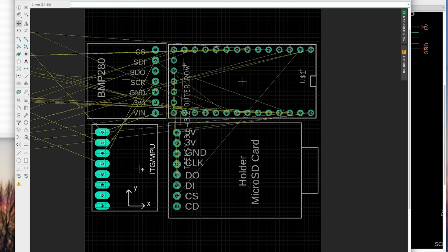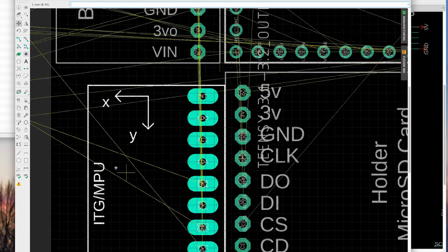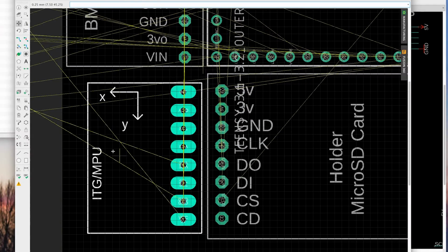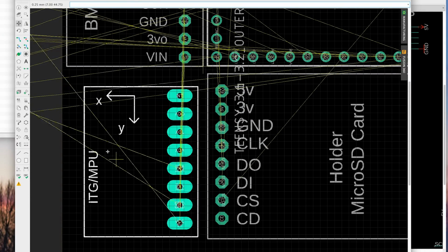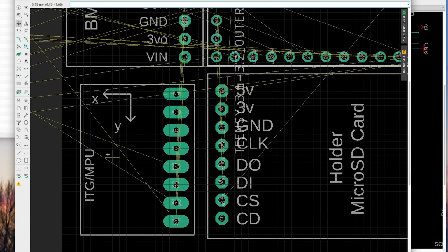Most PCB manufacturers are pretty good at what they do, but I do want to rotate this so that these mount points are towards the center of the board. So I'm going to right-click 2 times, 90 degrees, 180 degrees, and there we go. Now they are near the center of the board. I'm going to use the Alt key to get a little bit more precision in my movement, and I'll put it, I don't know, right there looks pretty good. Again, we can be pretty flexible with this stuff. So let's see, what should we do next?